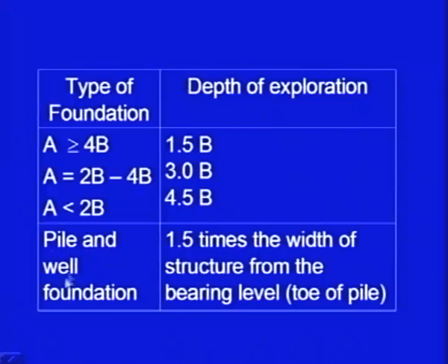So, the next one is pile and well foundation. For this, 1.5 times the width of the structure from the bearing level. Bearing level means the toe of the pile. From the toe of the pile, you have to go 1.5 times the width of the structure deeper. You have to go that much deep below the bearing level.